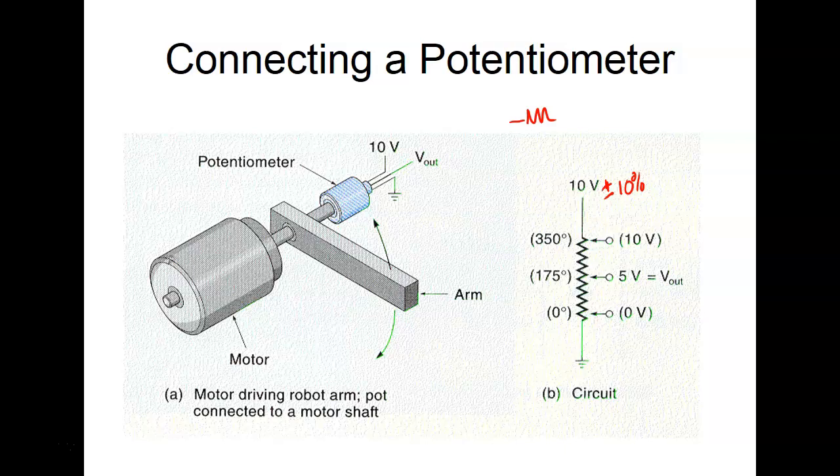So what would be the transfer function on this guy? Let's say 350 degrees, which is what they say. We take the maximum voltage you can ever get out, which would be what? 10 volts, and we divide it by the maximum degrees. So we take 10, the maximum amount, over degrees, 350. And what did you get? 57 millivolts per degree. Okay. This is not Ohm's law. This is actually real algebra, right?